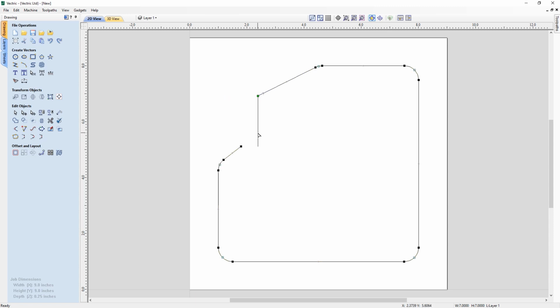same spot. And now for the point at the bottom, we can also use the features of Smart Snapping to grab the point, move it across, while still holding it and hovering over this point. We have now identified that as a Smart Snap point. We can now move up here, and as you can see, it's found the adjacent line so that we can now drop there, and it is now perfectly in line with this. And by likewise pulling this across, we can now link them back up together. We can right click to disable the node editing mode to put us back into a normal position.